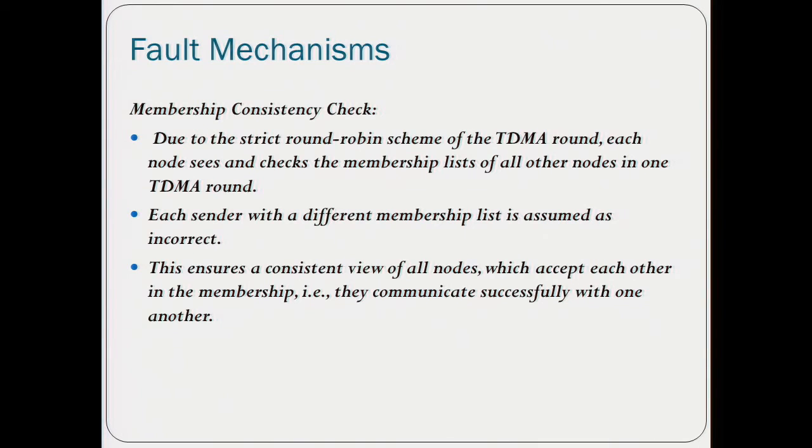And one is the one that is most preferred in this kind of application, the fault silent model. What is the fault silent mode? It means that if he is broken, he's not going to say anything. So it's mute, like you put mute on your microphone. So what happens? How do I detect that he is broken? Well, if I have a supervisor that checks the slot, and the slot is empty, it means something bad has happened to him because he's not responding. So you have to do something about it, but you realize that something has gone wrong.